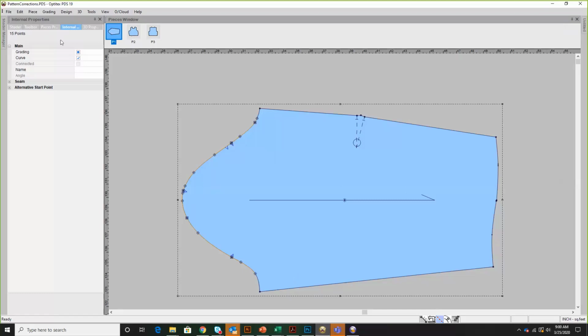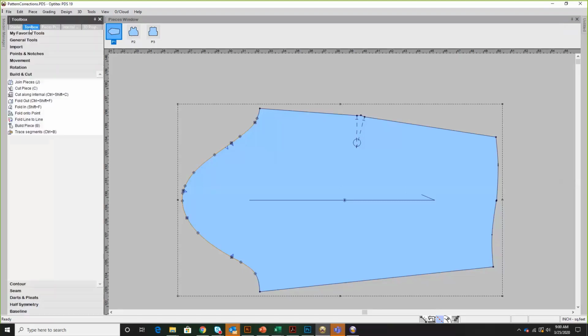Yeah, that's because I am a big proponent of shortcuts. But the easy way is to go into movement, and it's under here, walk. On the right-hand side, in parentheses, is the shortcut for all the tools. Walk is a great one. It's one of what I call the dumb shortcuts: W for walk. There's a lot of other functions that can be done that way, as you see there. Almost everything has a shortcut, and if it doesn't, you can actually create your own custom shortcuts.